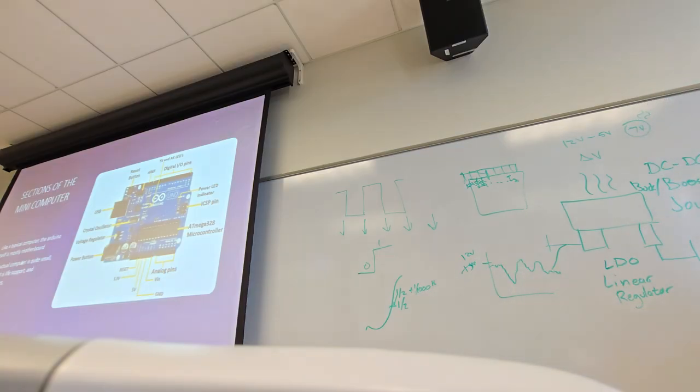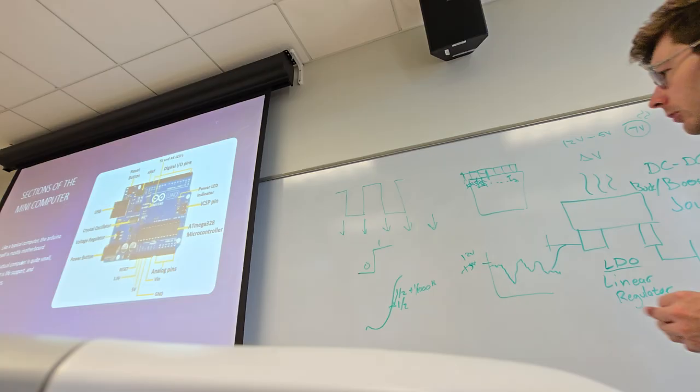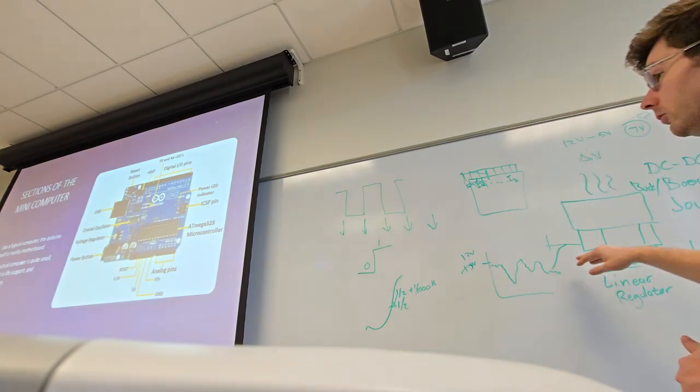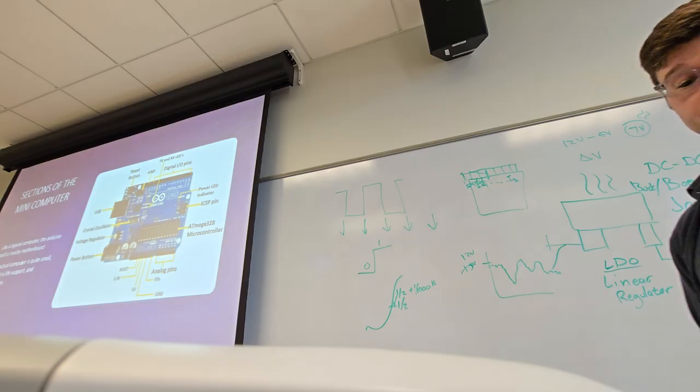This is actually a very complicated thing to do. In AC electronics, all you need is a transformer. That's it, super simple, dead simple. Windings in, windings out, right, gives you that ratio. But in DC electronics, it's not so simple. We can't use a transformer for that. We have to use these complicated, weird electronics like LDOs and DC to DC buck boost converters. But at the end of the day, they just turn one power voltage into another power voltage.